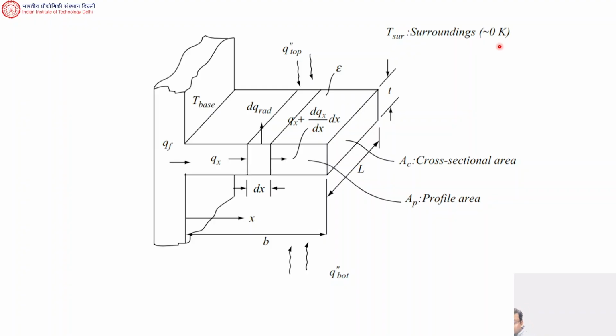So you cannot dissipate heat by convection. That's a problem. You can dissipate heat by radiation, but you want to increase the area through which the radiation will take place. Well, radiation will also depend on area. So that's why you add fins.